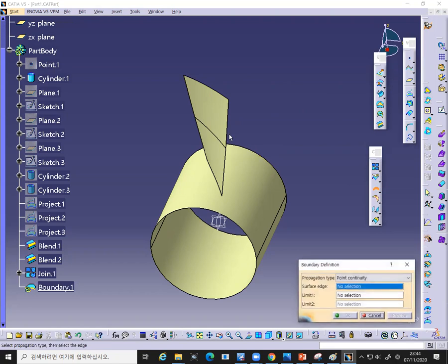But when we use a boundary, it's completely extracting here and here. The problem is, when we completely extract, I want to make a radius only here. So it's not possible to use 3D corner when everything is extracted. If we use this one here also, that is making a corner, and here also it is making a corner, so this is not correct.